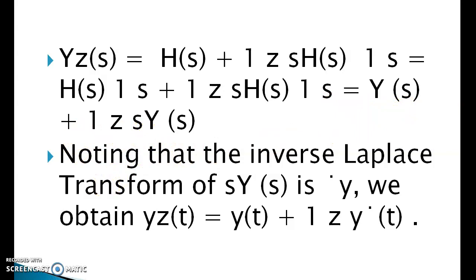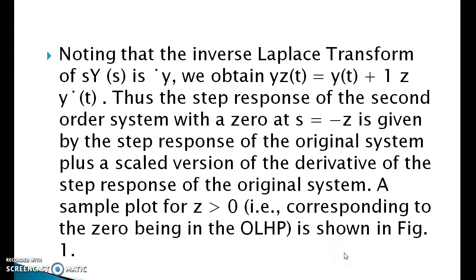Noting that the inverse Laplace transform of sY(s) is y-dot, we obtain yz(t) = y(t) + (1/z)y-dot(t).